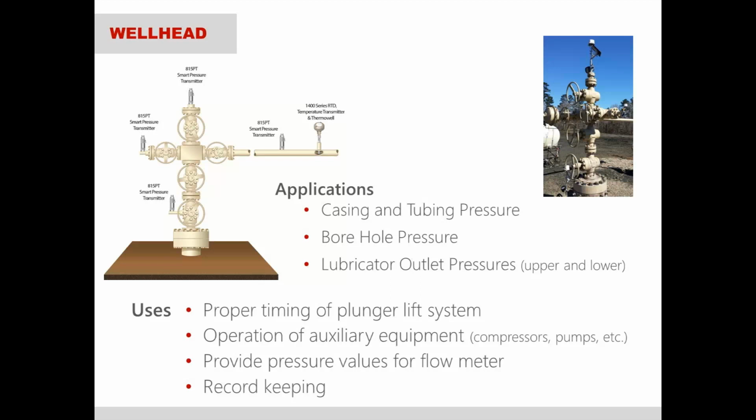And so basically what the plunger lift system is doing is it's a clean and efficient alternative to a wellhead blowdown, where in the past what they would do is they would allow the liquid to build up pressure, and then they would open up a valve that would spray that liquid and a little bit of gas into the atmosphere and relieve that pressure. So with some of the focus on being more clean and efficient now, lots of times you'll see a lubricator plunger lift system put in place.